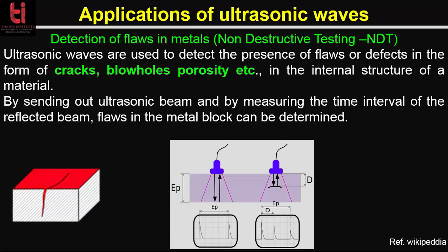This is an essential part of the modern manufacturing process. Most metals can be inspected, as well as plastics and aerospace composites. Normally we use lower frequency ultrasound, like 50 to 500 kHz, to inspect less dense materials such as wood, concrete and cement.